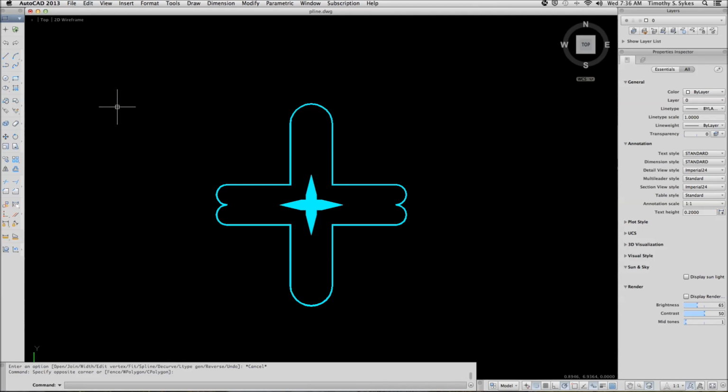This is a combination of two exercises, 12.2c, more complex polyline editing tools, and 12.2d, working with polyline editing grips. I'm in the PLine drawing found in the Steps Lesson 12 folder. Polar tracking is turned on, my polar snap is turned on, and my dynamic input is turned on.